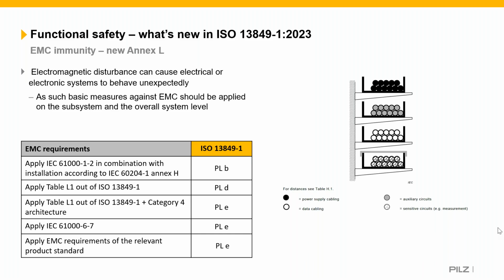If you're going to score the PLC, when you're doing that, you're attributing the score for EMC against the PLC, that can only be done once per safety related control system. So there is, like I say, a whole table which gives you the guidance on that in Annex L.